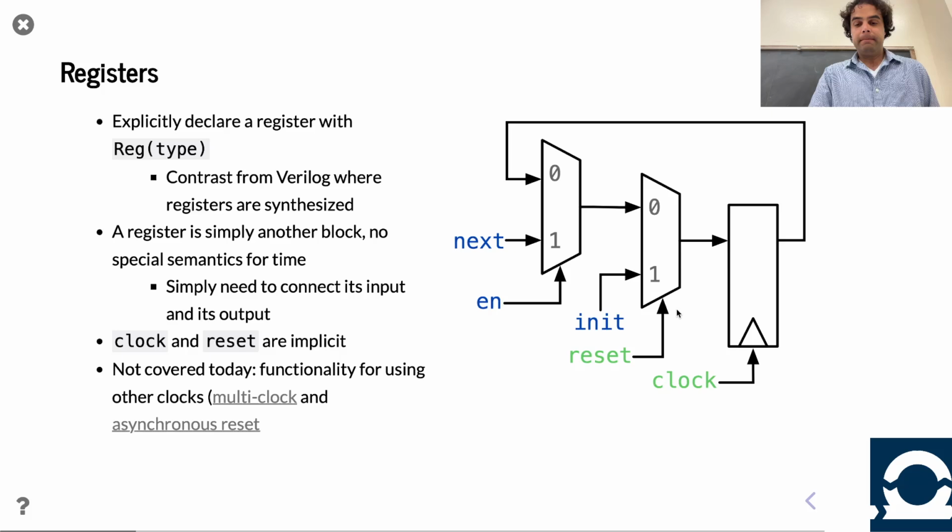And so we talked about before in this class that, as designers in Chisel, we just see the value register, both its input and its output. Things like reset and clock are hidden from us. They exist. We see them in the Verilog, but they're implicit, meaning they're automatically instantiated, automatically connected, automatically passed through our design. And that's done because it's a common case.